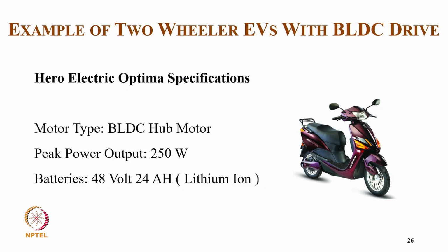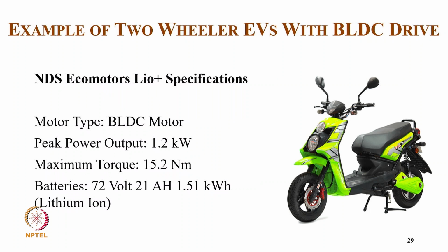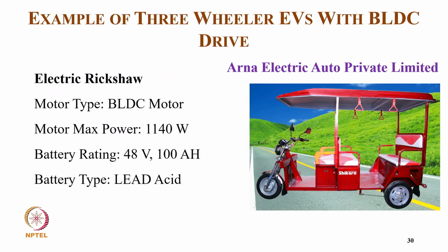They are very economical. Even if you charge once, it can go around 65 kilometers on a single charge, using even less than 1 unit of electricity. Then this is another motor of 250 watt by Hero Electric Optima specification. Then the Platino Skyper of 250 watt BLDC motor at 60 volt. Then the NDS Eco Motors Leo, where we use a BLDC motor of 1.2 kilowatt with a battery of 72 volt and 21 ampere hour.